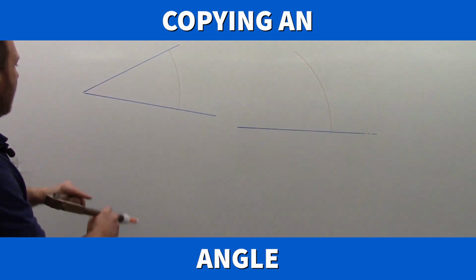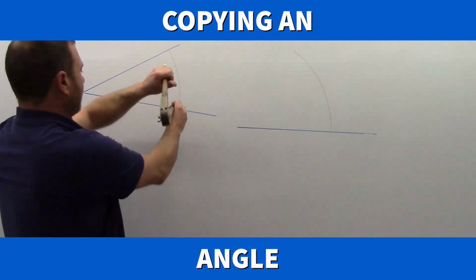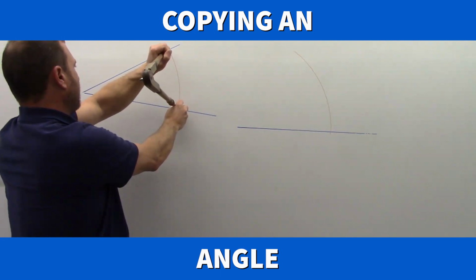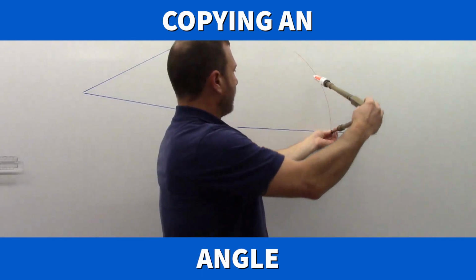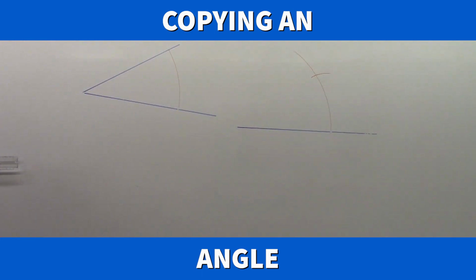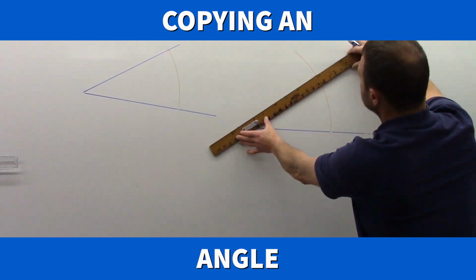So if I've taken my radius and swung it over there, if I now take the arc length, or really the chord, the straight line, because my dividers or compass is a straight line, and I pick this distance up, I'll transfer it to the other side. And now I have a cross point with the same arc length and the same radius, which means it's the same angle.